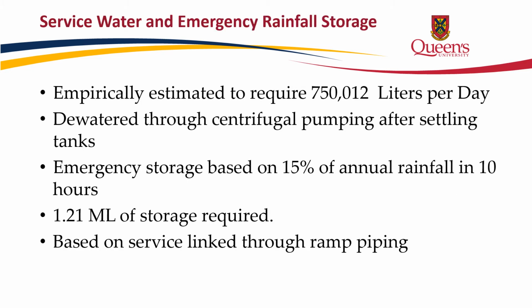The service water requirements of the mine were estimated to be 750,000 liters per day via an empirical formula. The water will be pressurized in a secondary sump storage unit after dewatering and made accessible to working areas and key points in the mine via auxiliary piping.